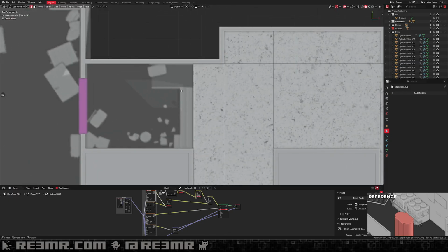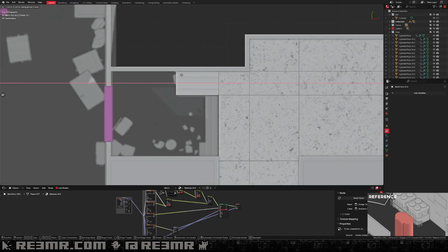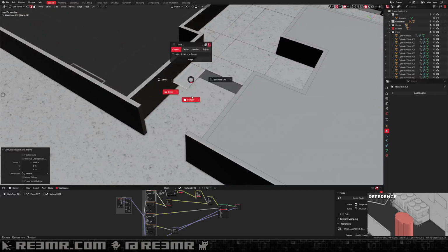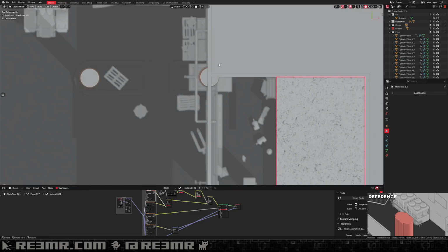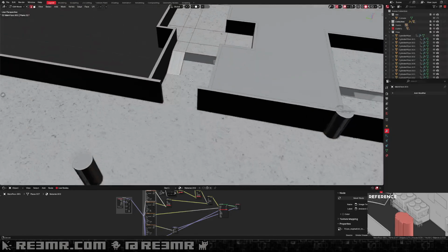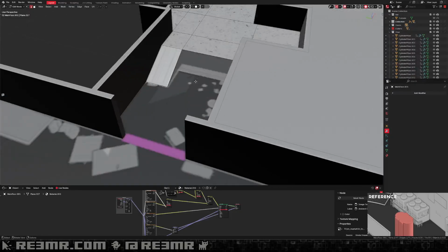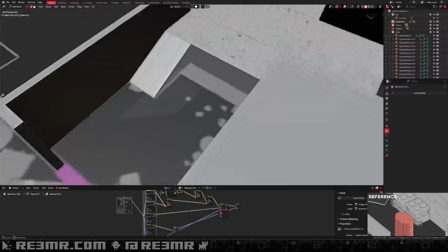And probably a staircase. I'm just going to extrude that and pull that down to the surface. Uncheck align to rotation. It looks like there are 2 steps here, which would be kind of strange.